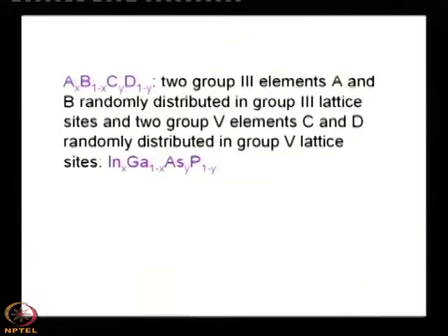But the thing is the same. If we are doping boron in silicon, then boron takes the sites of silicon. And same is the case here. If I dope boron, can it take the interstitial position? Then after it goes to the vacancy. No, no, it is the interstitial position as well. Don't mix up these two things. It is the regular lattice site.